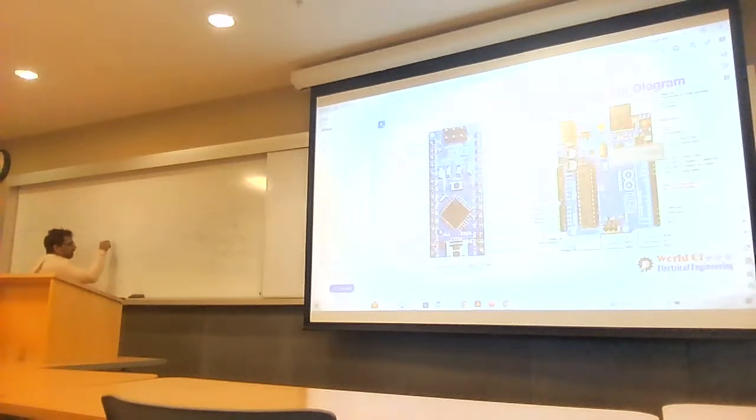For example, a radio station or every mobile company has a particular bandwidth. If our clock speed changes, then my signal will not be in that bandwidth. It will change its bandwidth. So we need a closed loop system that can produce high frequency and be stable. So the PLL is the circuitry which can produce ultra high frequency along with a stable frequency. Okay, this is the motivation of the PLL.